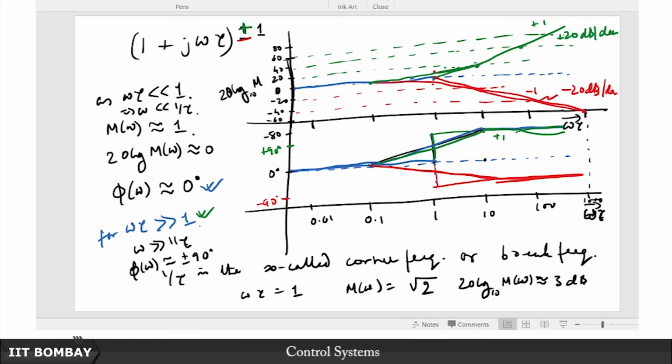And then some people will insist that we also want to bend around these corners and smoothen it out, but again really not a big deal. Some other textbooks would suggest that instead of going 1 decade, why don't you just go half a decade, or rather 1/5 rather than 1/10, go 1/5 of the way down and 1/5 of the way up and then join these points.